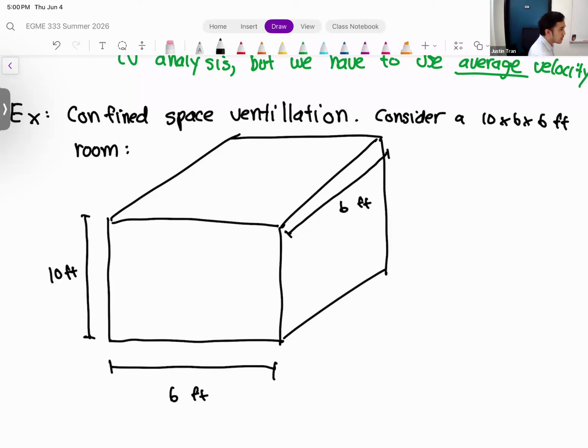Ventilation is especially important for applications where maybe you're doing some type of work in this room where particulates are going to be in the air, and so you need to ventilate it so that those particulates don't cause people breathing problems. One common application for this, that I've experienced a little bit myself, is industrial paint applications where you're spray painting a lot of stuff that puts a lot of particulates in the air, right? And so you really need a room with proper ventilation in order to perform that work. Otherwise, you're going to be breathing in paint particles, and it's going to cause a bunch of health problems.